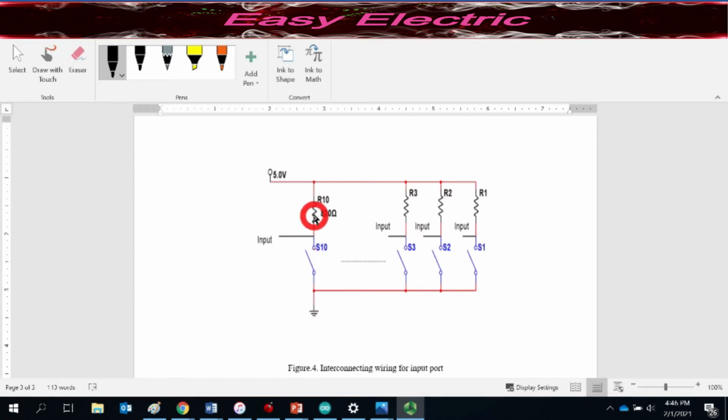The other side has this resistor bar, which is 820 ohm. The common pin of the resistor bar is connected to 5 volts, and the other side is connected to the other side of the switch, and our input is this common place that we have. So let's see what's happening in this circuit. Whenever this switch is open, you have these 5 volts, so in the input you have digital 1. Whenever you close this switch, you have 0 here, so you have digital 0.